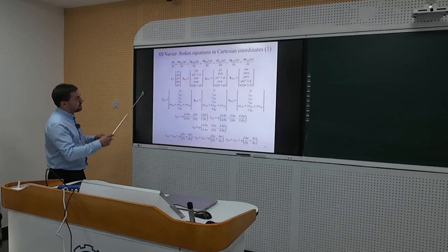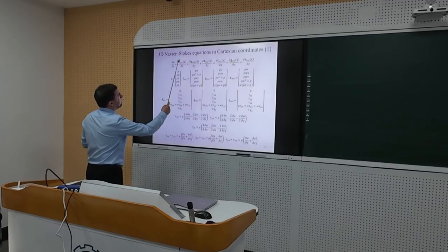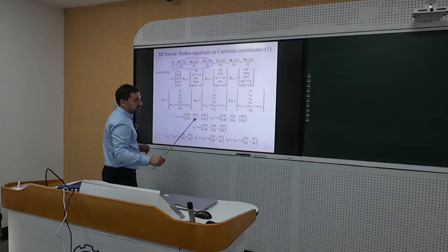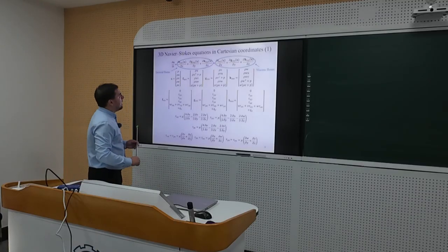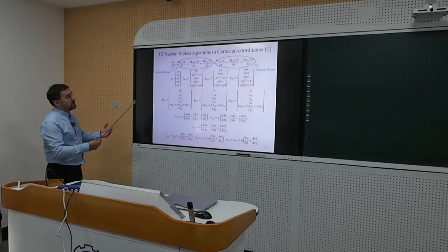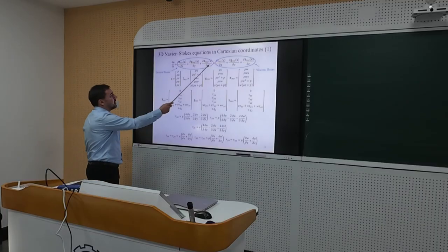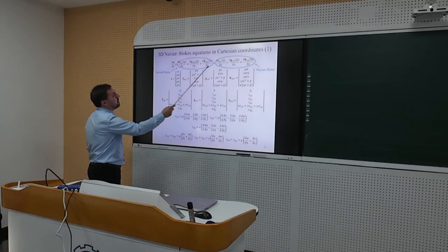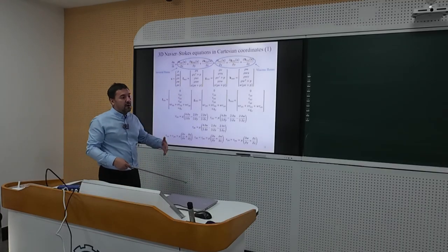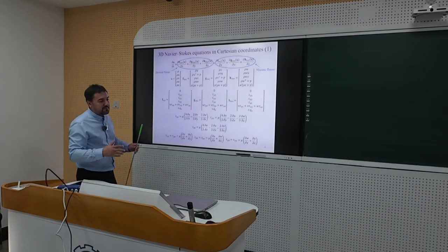So topologically, in the Navier-Stokes equations we have the inviscid part, inviscid fluxes, and viscous fluxes. From a numerical point of view, when you try to solve it, generally the numerical algorithm comprises two parts. First of all, we should know how to solve the inviscid subsystem, so Euler equations. That is why I told you that everything starts with Euler equations. If you know how to solve the Euler equations, after that you can solve many other models.